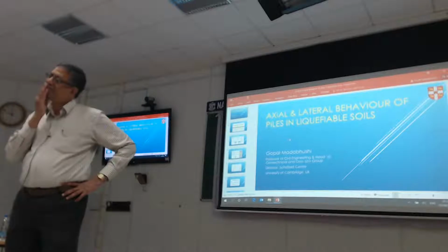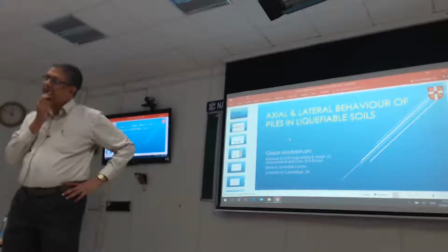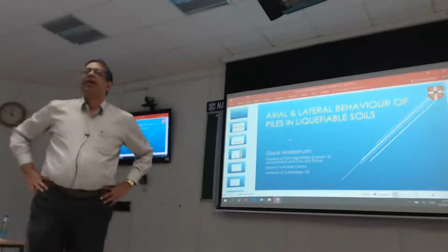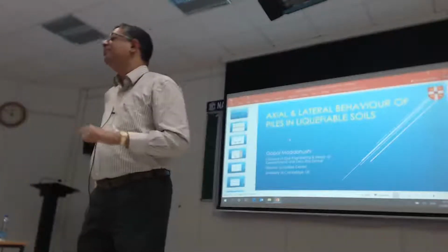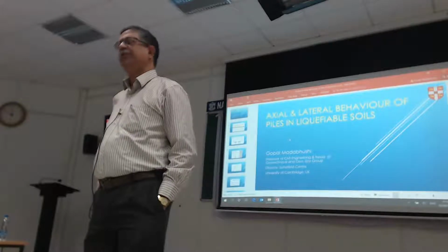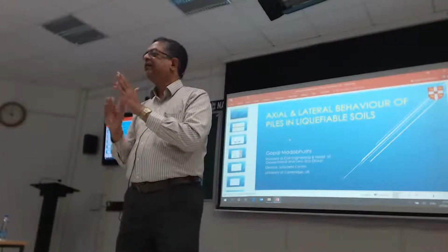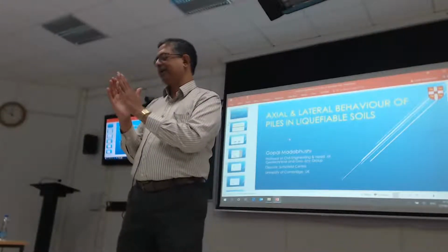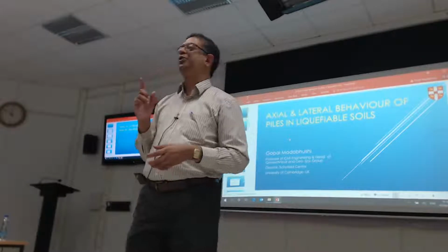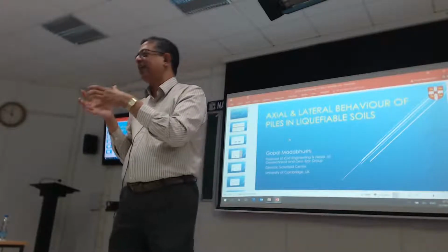So can we expect a pile group with smaller spacing to be stiffer than one with a larger spacing? I'm tempted to say not as much as you think. If you imagine that the pile groups are closely spaced, the reason you're thinking that the closely spaced ones can't buckle so much is because they tend to act together. That's only true if these piles are all trying to buckle inwards, where the soil is getting trapped.